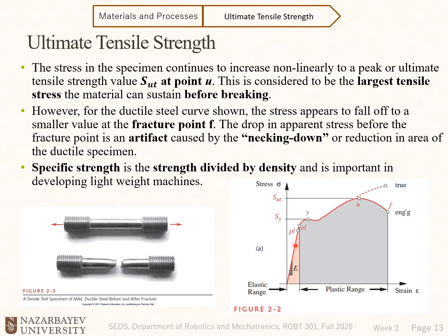You see, this part is non-linear to a peak, or ultimate tensile strength value SUT at point U. So here, at point U, you have the tensile strength SUT.